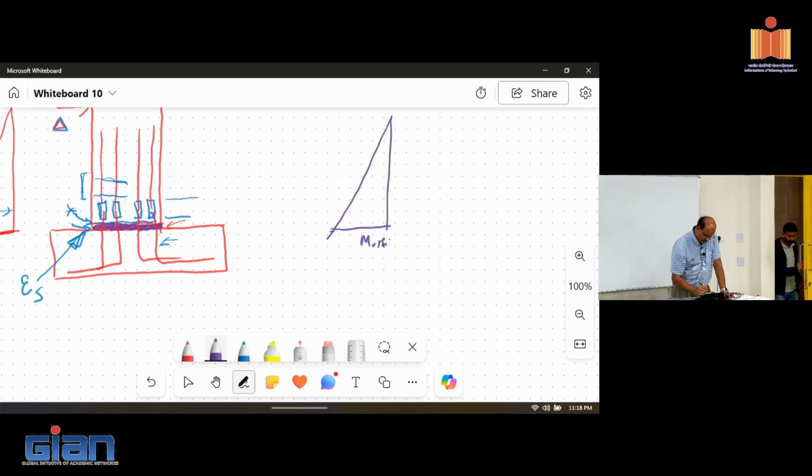Now you have slightly higher moment developed because of strain hardening. So you may get more shear into the wall as well, and therefore the shear can become critical. So especially if you have a short beam, short walls, the shear issue can kick in, and you have to account for that in the design properly.